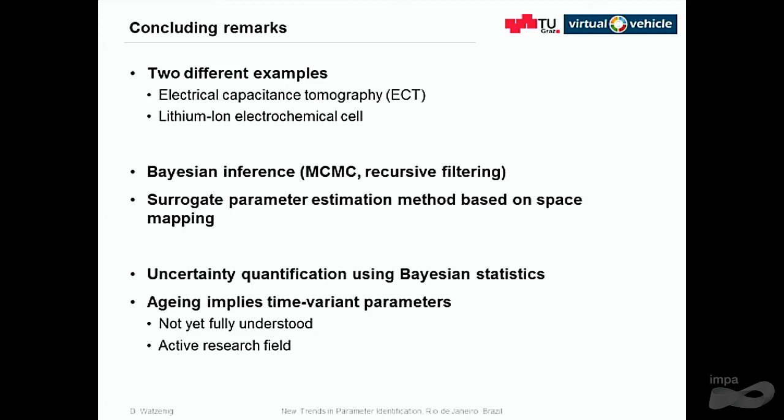We have to work together, and that's the good thing. Industry in Europe is paying quite a lot of money for working out an optimal electrochemical model which is able to predict safety features. That means predicting the temperature in a very accurate way, and also predicting certain aging effects over time, in order to figure out what happens with a certain stress profile, a certain load profile over time when you cycle in a hybrid car, in an electric car, or even in different classes of cars. Let's say a small car, a larger car, or a premium car.